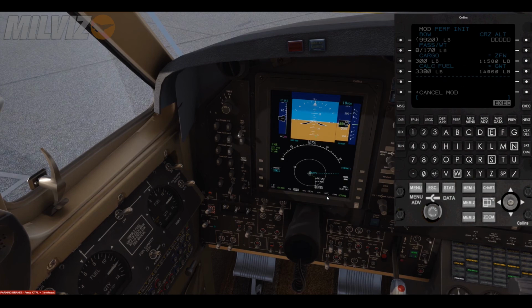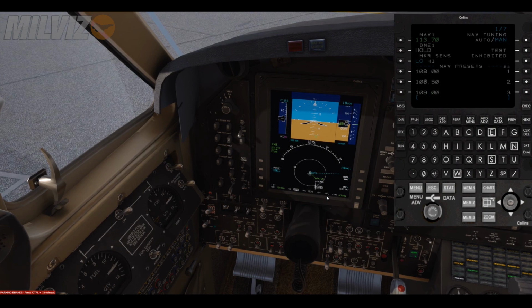And finally, we're going to fly this route at 15,000 feet. Now I can type in 15,000, I can type in F15,000 or FL15,000. I like to save myself keystrokes, so I go F15,000 and execute that. Okay, that is a basic flight plan loaded into my FMS. The other thing I might want to do before takeoff is to go ahead and set my VORs to auto tuning. So that way the FMS will take care of tuning my VORs for me.